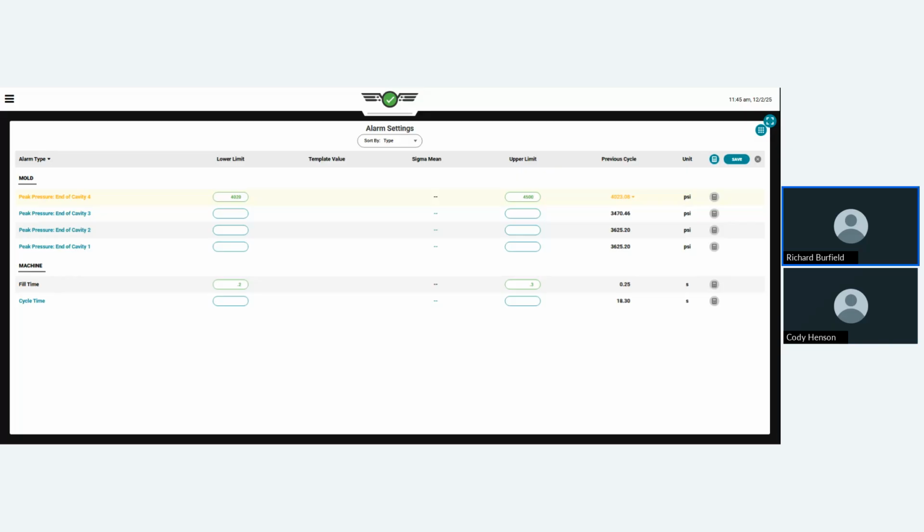Okay, so that might answer the other question. Is there a signal output for warning limits? Yes, that's where it ties into. You could have it, I believe you could also have it perform a secondary operation. For example, maybe if you wanted a secondary deposit position for your robot for additional inspection. Okay. Other than that, it's mostly used to signal a yellow warning stack light. Yep, a caution or a yellow light, like you said, the light tree or something like that.